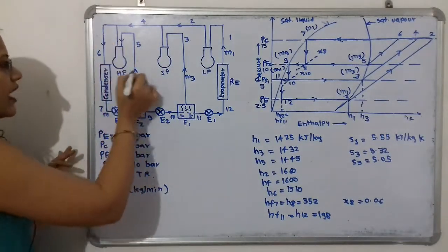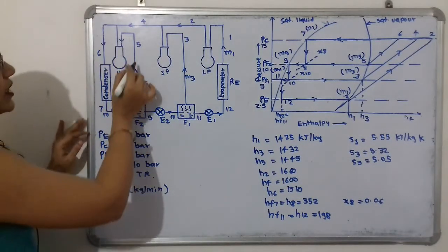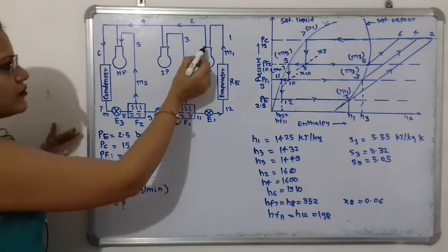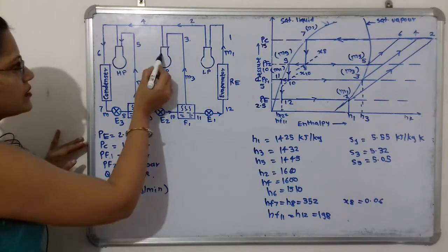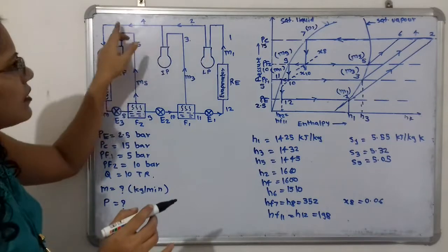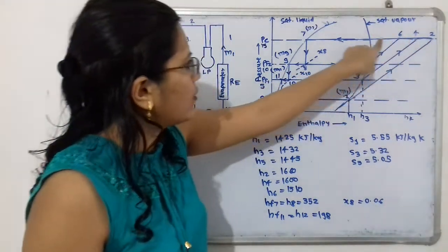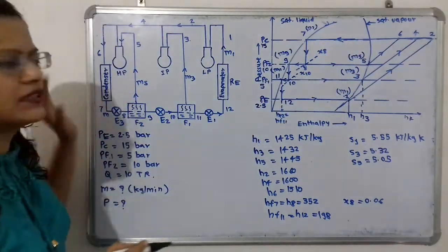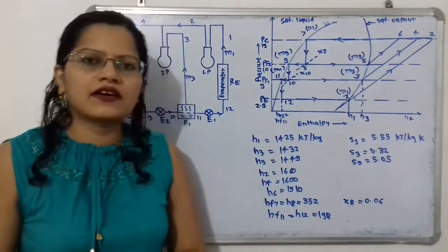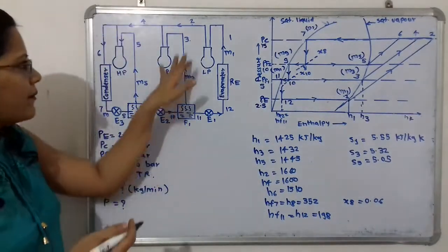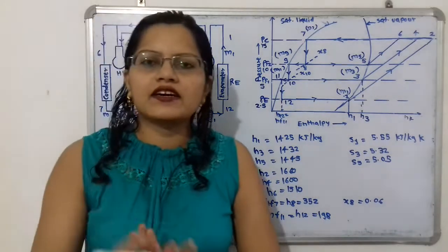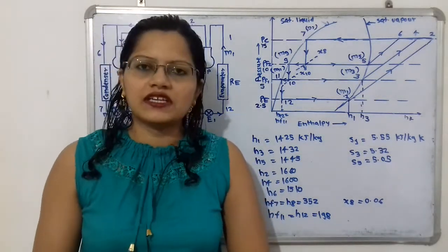After this high pressure compression, if we observe, the refrigerant leaving after compression from the low pressure compressor, intermediate pressure compressor and high pressure compressor are meeting or mixing with each other. And all are moving to the condenser for the condensation process. So what is happening in the condenser? These refrigerants at high pressures are getting cooled and getting converted up to the saturated liquid state.